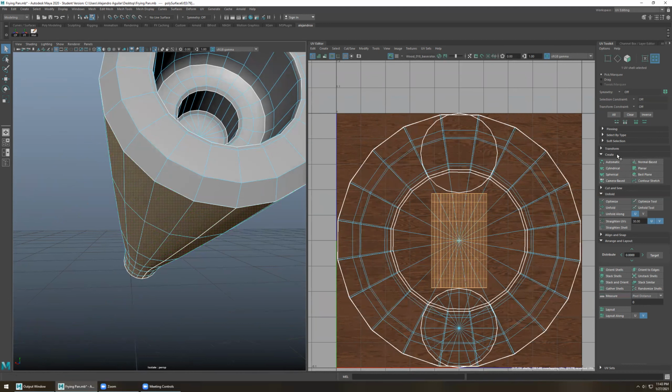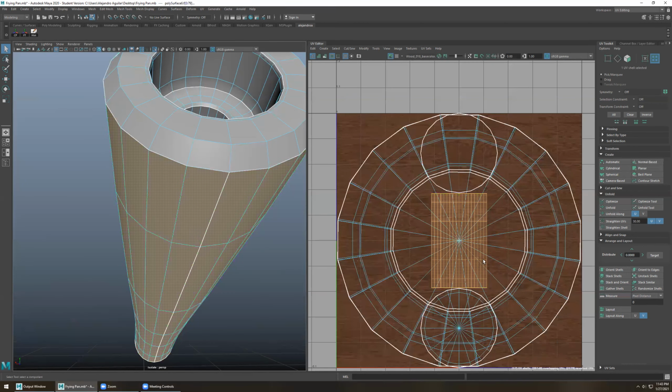The create unwrap and unwrapping in general is just meant to help you with your UVs. You technically have them already unwrapped when you make your cuts. So you can just skip most of it and just unfold, optimize, unfold. If you want to straighten it, there you go.